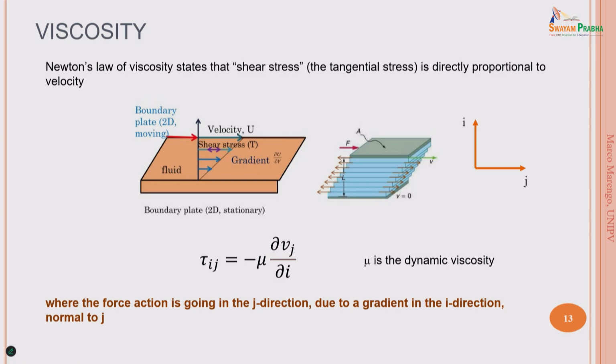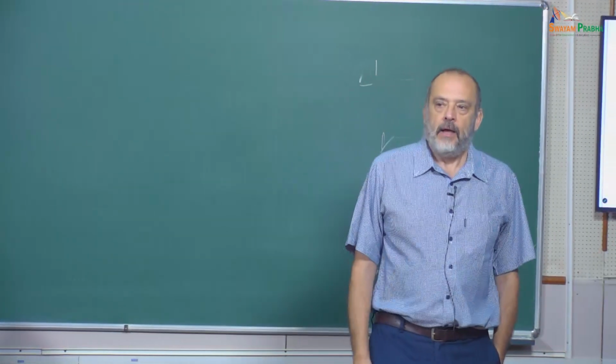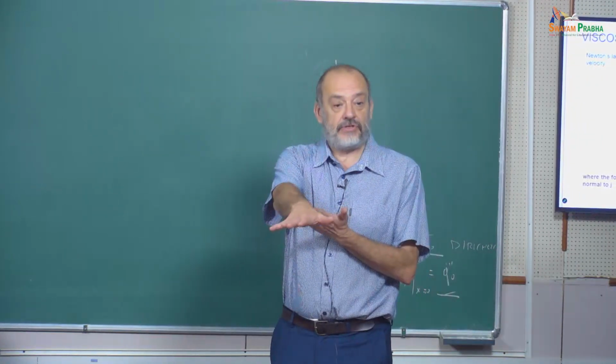So this is interesting, but it poses a problem because then the flow is moving. So somewhere there is a change from the main velocity to zero, because here is something and there is zero. So what's happening? In fact, we have a velocity profile of the motion when we are in the presence of a wall. And the fact that we have a profile means that the velocity is changing in the direction normal to the wall. And this is creating friction.